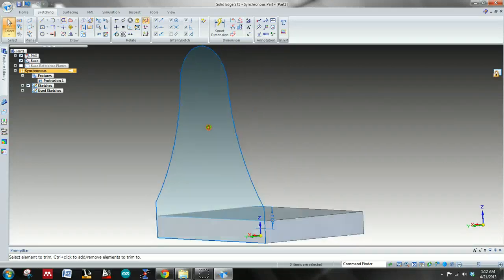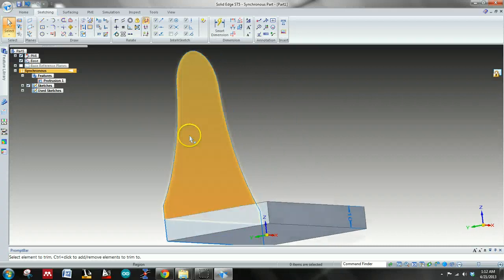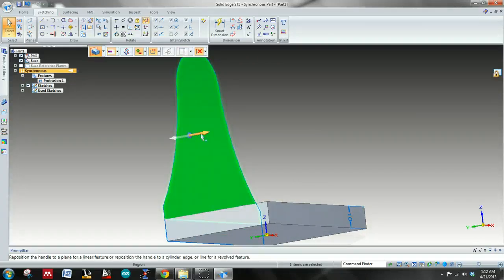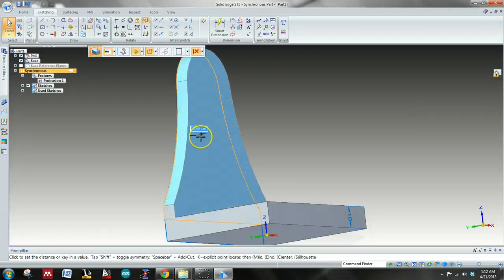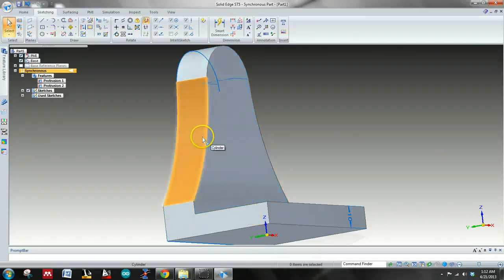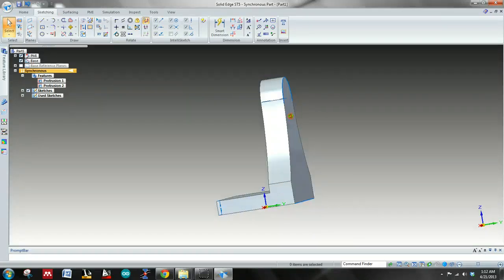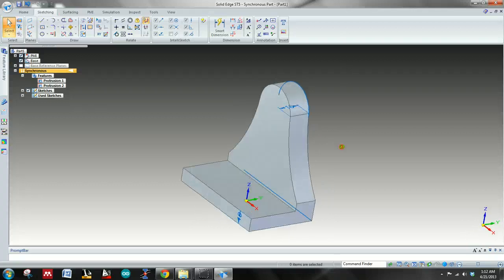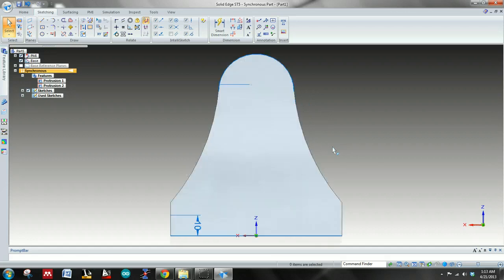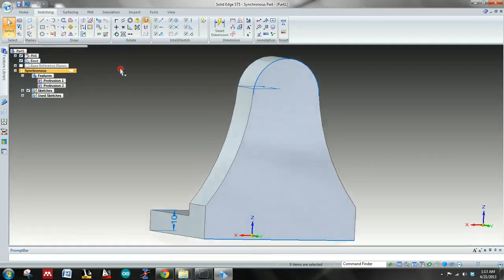So there we go. And now all that's left to do is to extrude this right here. So just click on it, click on this arrow, come forward with it by 16, and then there you have it right there. Okay, and so now we need to drill through the holes. So I'm going to come Control K,